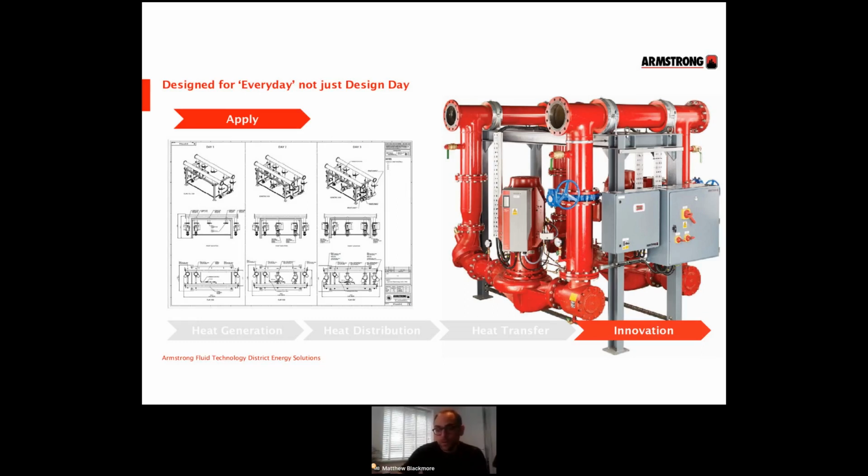Let's move the goalposts a little bit. Let's design for every day, not just design day. If we do that and we think about things in that mentality, we can solve a lot of these issues. Look at the drawing on the screen for reference. Pipework, controls, infrastructure, they're all in place for what will be deemed as design day. But then we have a phased introduction of pumps that are brought into the network as that load is dictating. So we can then maintain efficiencies throughout the entire build-out program. This can be predefined. It's demonstrated on the drawing. We can make a series of pump selections based on scenarios, but equally that can be changed at any given time.